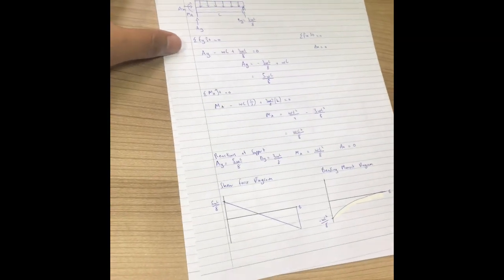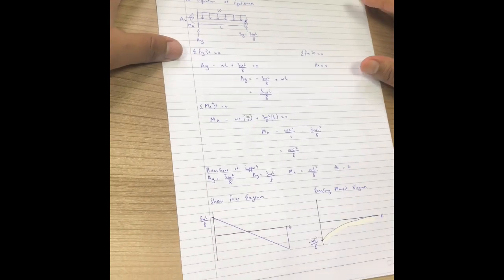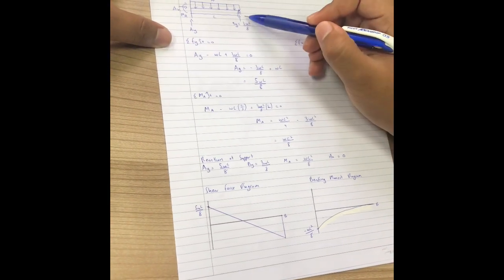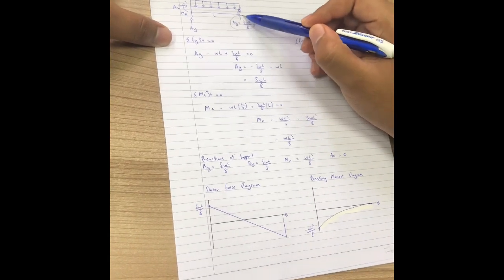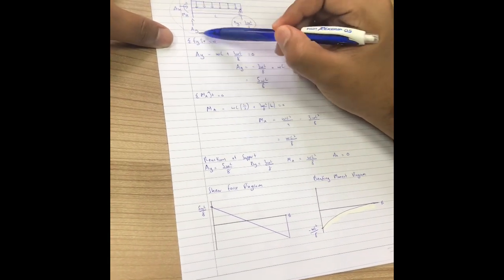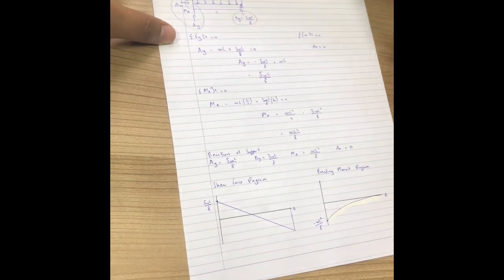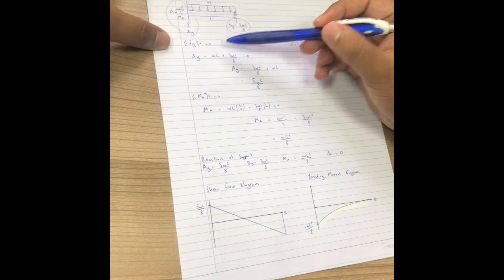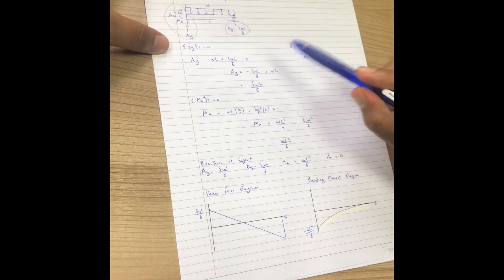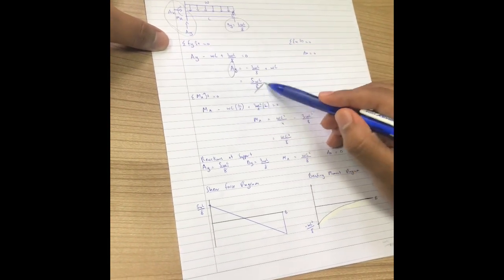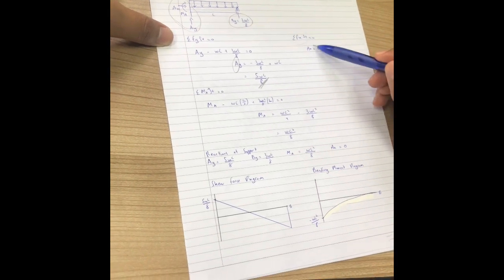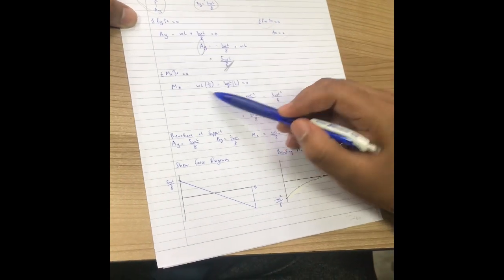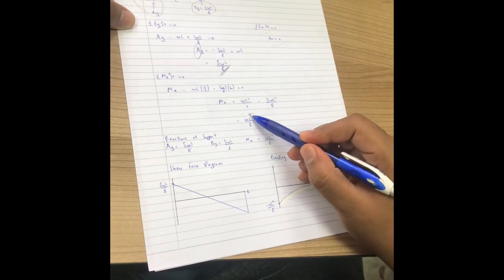And the last step is equation of equilibrium, and this is to find the other reactions, because now, as you know, we already got our redundant force value, so we can find the reaction of our other support. Okay, then just do a normal equation of equilibrium. First we do Fy. By doing Fy, we get the value of Ay, which is this value. Then we do Fx. Ax is 0 because there is no horizontal force. Then we do the moment. We get our moment. This is the value of our moment.